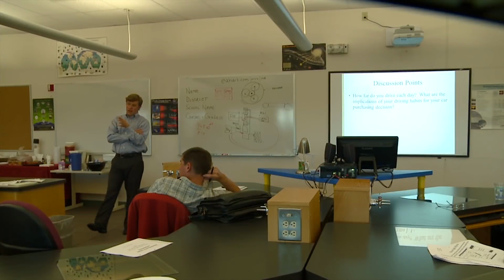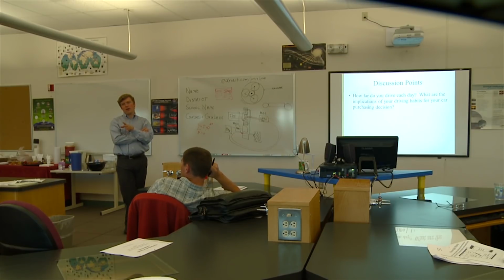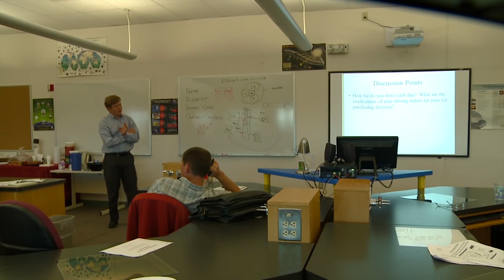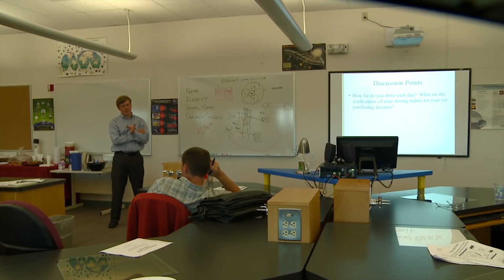So that's a really good point. And I'll tell you, the way that people have thought about dealing with that is what's called a second life of batteries. For instance, the U.S. Advanced Battery Council, USABC, has some definitions of battery end of life. The battery can do 80% of its capacity and 80% of its peak power. When it hits that point, it's no longer usable in vehicles because you have a car that instead of going 0 to 60 in 10 seconds, goes 0 to 60 in 16 seconds or something like that.